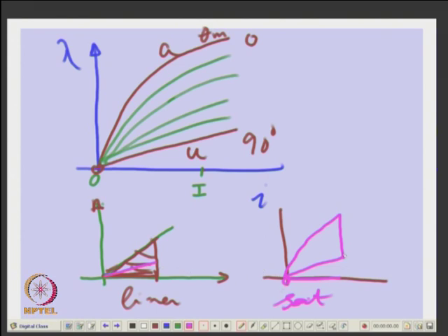You are passing a current, it is in the unaligned position and it goes to the aligned position, okay, and that is the path it will follow, right. So, it is as good as, in this case we can say it was unaligned, you have a constant current and you go here and come back here, is it not.